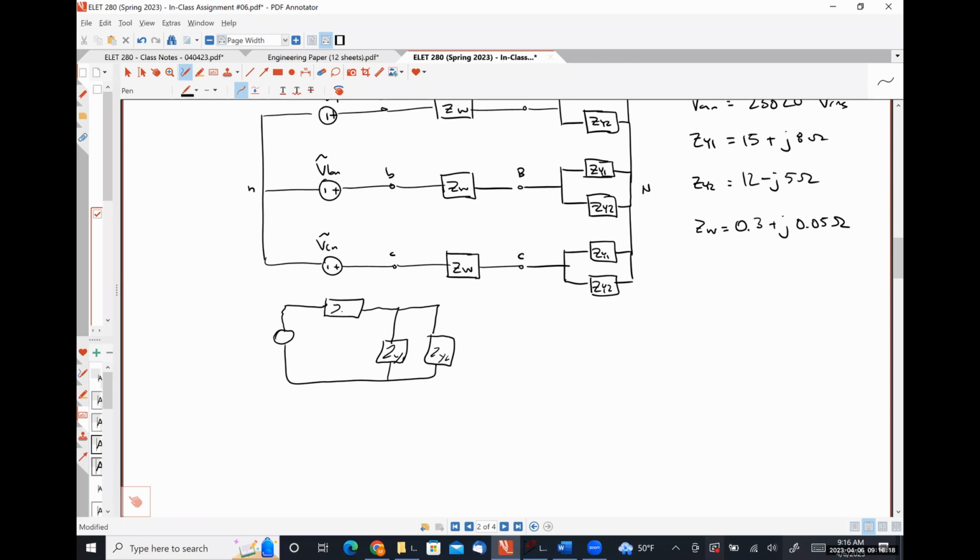Okay. They're all the same. Great. Wonderful. Perfect job. All right. So, anybody have a problem with this single phase equivalent circuit? Because it looks absolutely correct to me, right? It is exactly what we would expect if we had two Y connected loads in parallel and we're looking at it on a per phase basis.